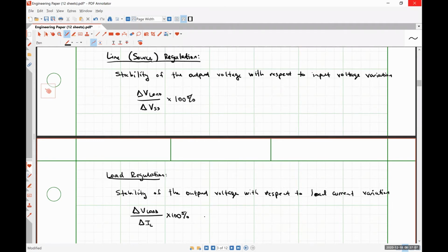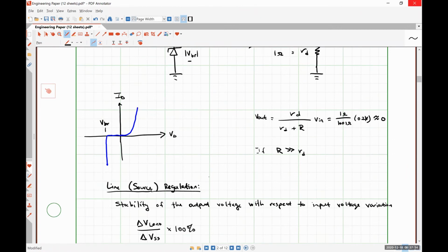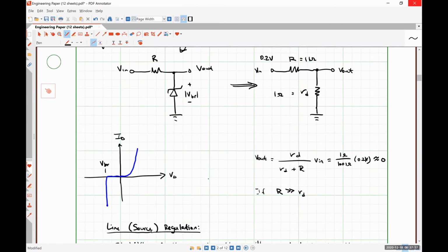All right, so voltage regulator circuits, fairly straightforward. Effectively, we only talked about Zener diodes here because we talked about using regular diodes to do it in a previous example problem. But we saw that for the cell phone problem that we worked, we had a relatively large change in our input voltage of 5 volts or half a volt. And we saw, I think, only 65 millivolts of change in our output. So we had pretty good regulation there.